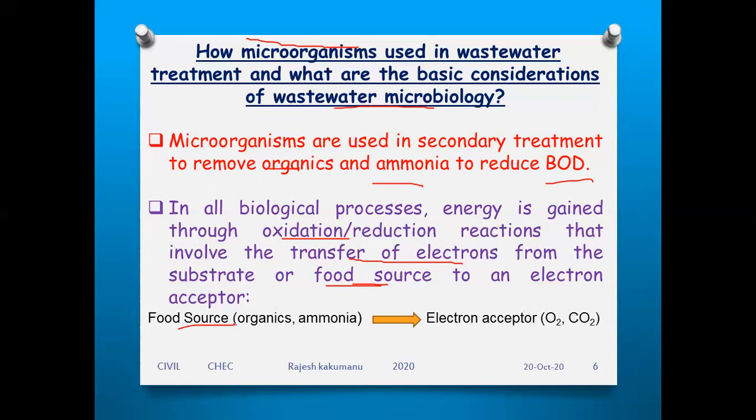In secondary wastewater treatment, the food source means the organic material plus ammonia. The food sources, that is the organic materials or ammonia present in the wastewater, give rise to the electron acceptor, oxygen plus carbon dioxide.